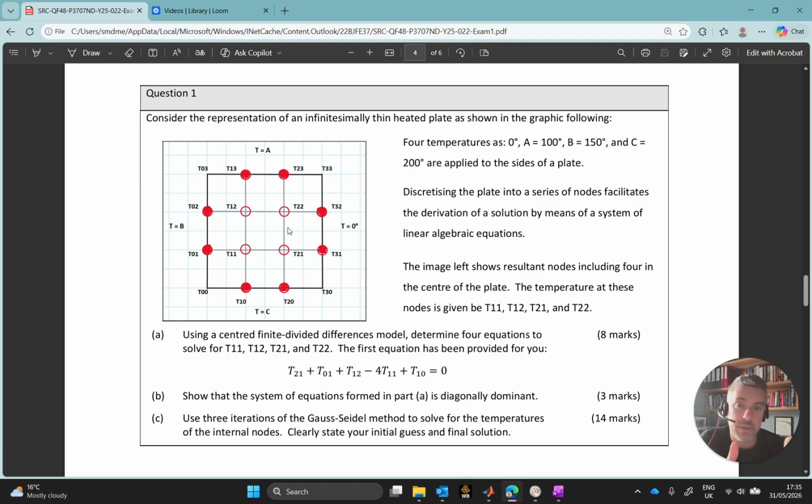So effectively it's a discretization of this kind of heated field, which would otherwise be solved analytically using Laplace's equation, I believe, for the heat transfer across the plate, which is a partial differential equation with one part in temperature being a function of time, and then the other function being space, whether it be x and y in this infinitesimally thin plate.